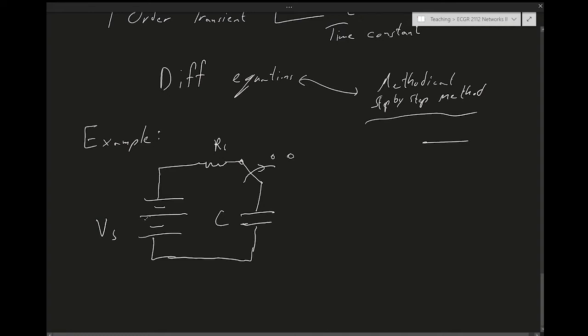And then when it gets charged to a certain voltage, when the time comes, the switch gets thrown to the other direction, and all the energy in the capacitor gets dissipated in the resistance that represents the lamp, let's say, lamp resistance. This discharge in the lamp resistance causes the lamp to flash.